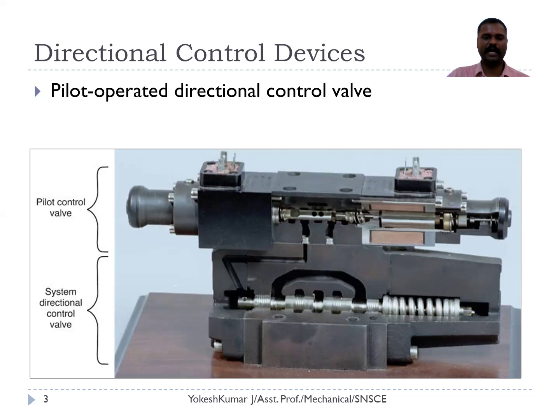Hence, no manual force or lever mechanism is used in the valve. We only allow the pressurized fluid to change the position of the spool. This type of valve is called a pilot operated direction control valve.